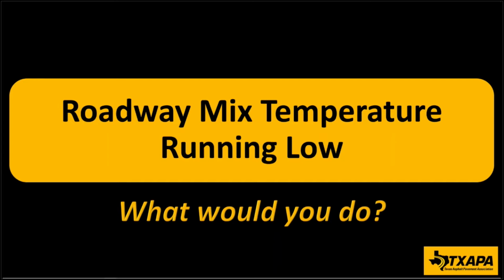Well, if the plant infrared is in fact giving correct answers, we would double check that with a minimum of a Fluke infrared camera. When you're dealing with temperatures, the cheap old Walmart version doesn't work. You need to purchase very sophisticated infrared cameras or infrared temperature thermometers. I recommend Flukes or FLIRs only. Gotcha. Yeah, and that's good, we talked about that last week, about double checking that thermocouple.